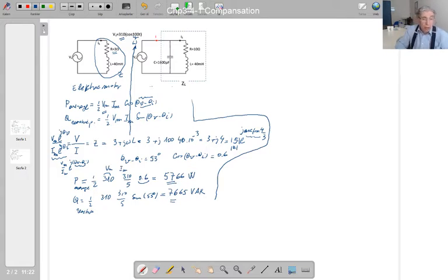Now I am saying this power in this circuit, the useful power is going to be the same for this motor part here in this circuit and this. Why is that? Because I am saying the voltage here for this motor is the same as this, isn't it? Because this is in parallel. That means this voltage, this load, this motor voltage is the same as this capacitor voltage. Also, this is the same as the source voltage. So, voltage does not change.